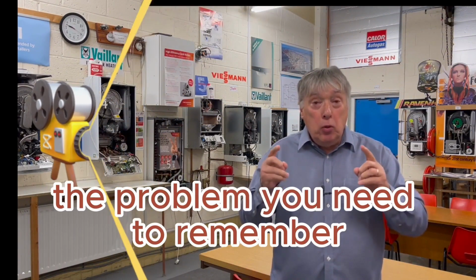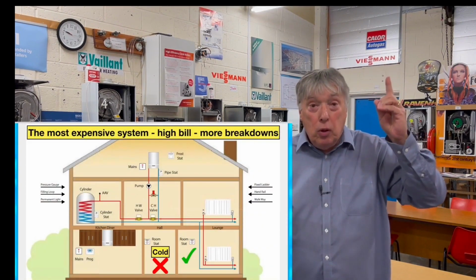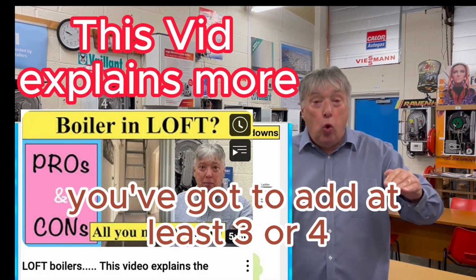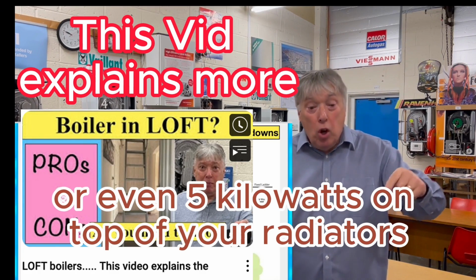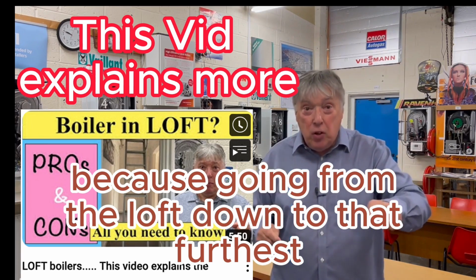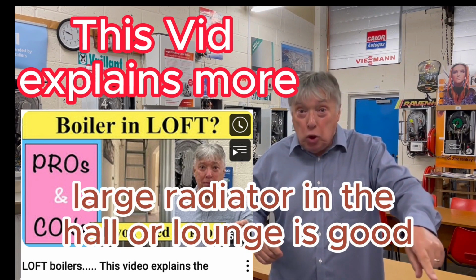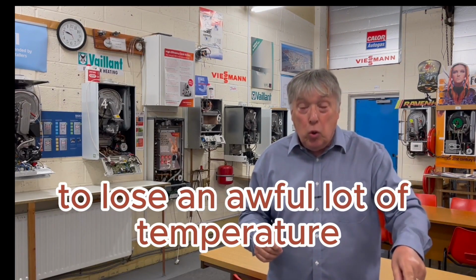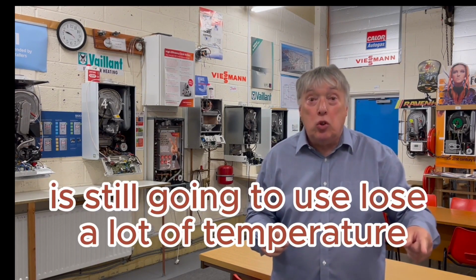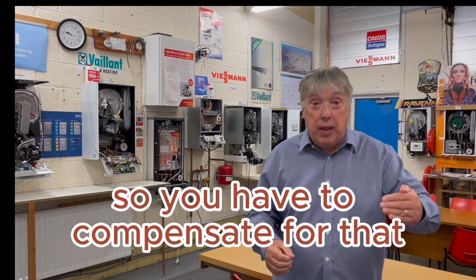The problem you need to remember is that if your boiler is up in the loft, you can't do that. You've got to add at least 3 or 4 or even 5 kilowatts on top of your radiators, because going from the loft down to that furthest large radiator in the hall or lounge is going to lose an awful lot of temperature. Even after lagging, it's still going to lose a lot of temperature, so you have to compensate for that.